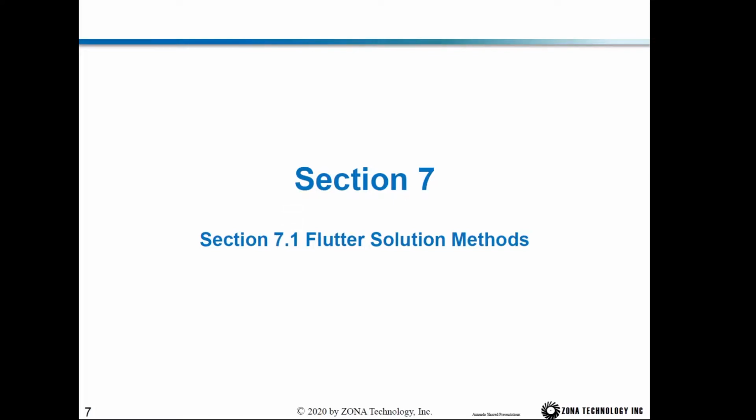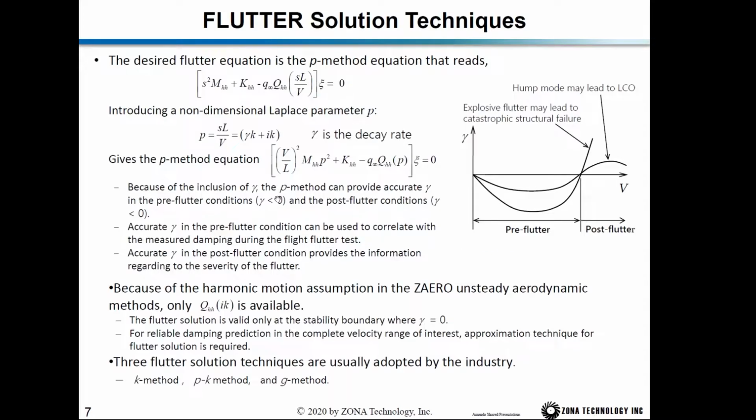So after we have the ASC matrix and we have the spline mode, the ASC matrix times the spline mode will give us unsteady aerodynamic pressure, and then we can convert the pressure into forces. Then we can pre-multiply the forces by the transpose of the motion matrix. That will give us the generalized aerodynamic forces called GAF. And once we have GAF, we can establish the Flutter equation.